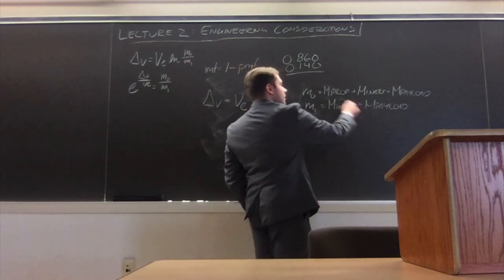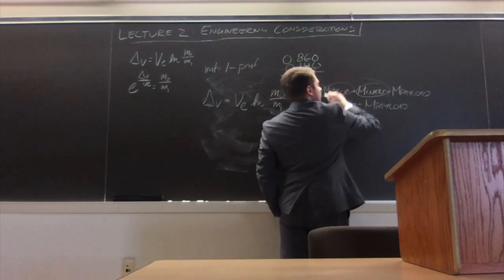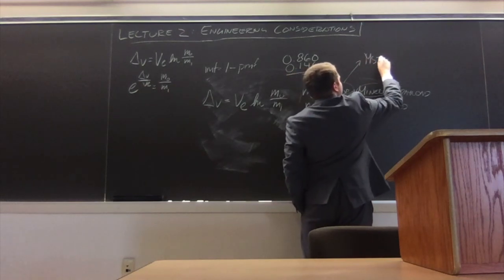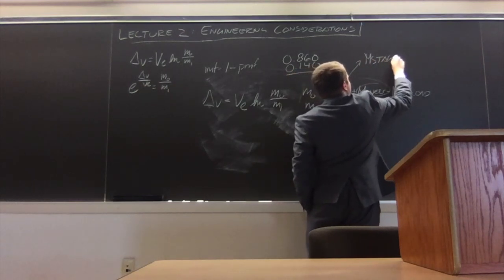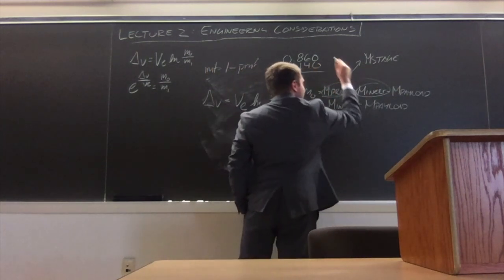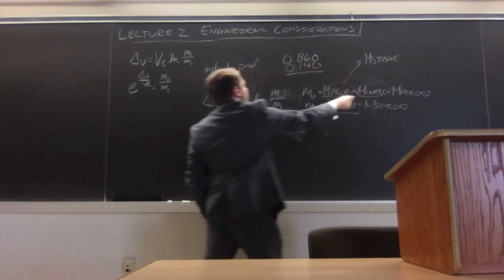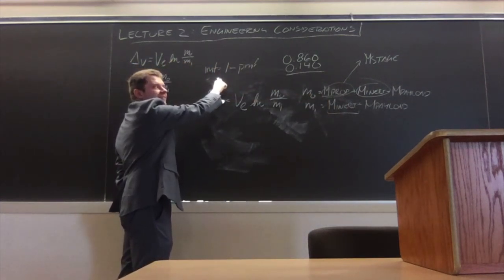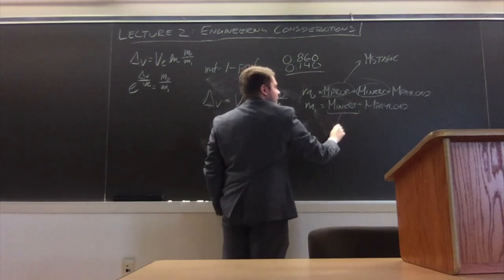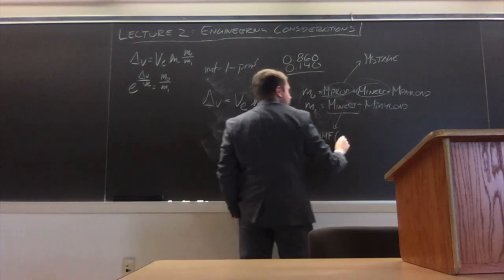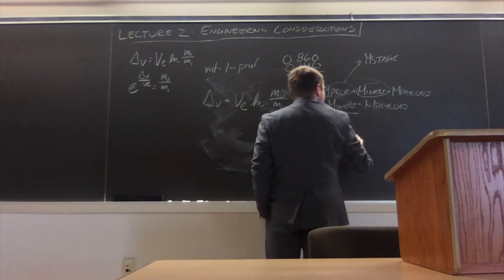In fact, we can look at the mass of the propellant and the mass of the inert, and combine it to a new factor called the mass of the stage. And then, of course, what is the inert mass as a function of the whole stage? The inert mass fraction. So all of this then becomes the inert mass fraction times the mass of the stage.